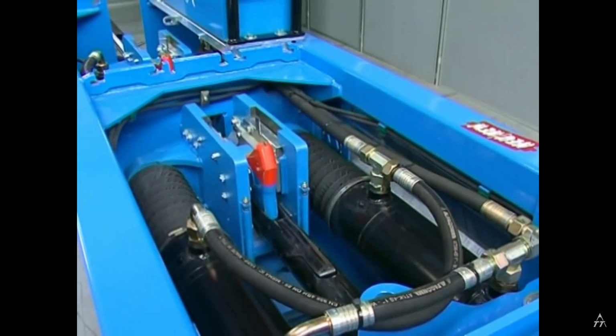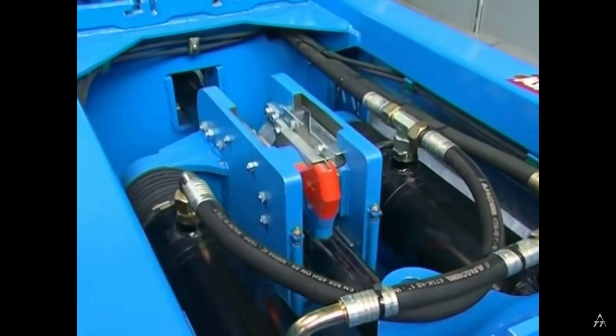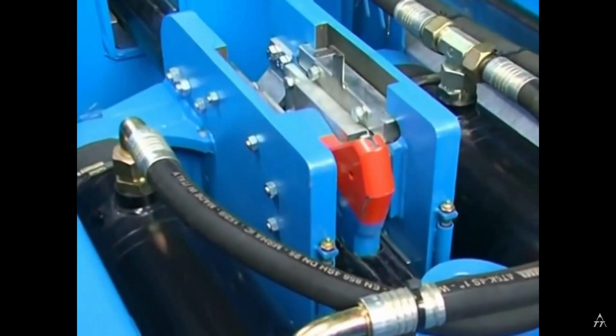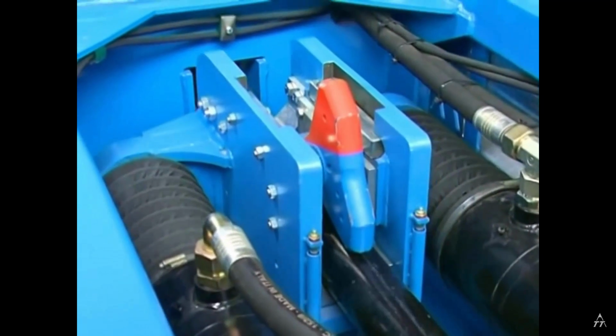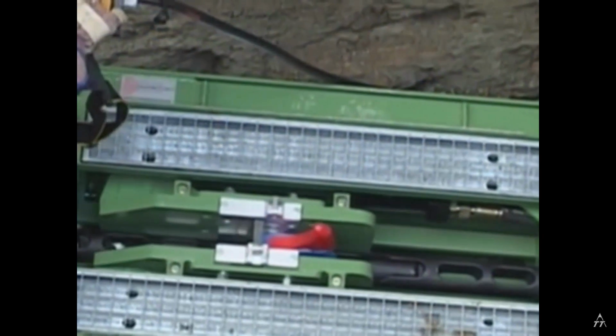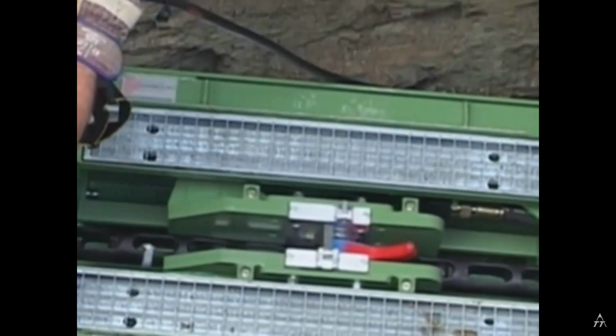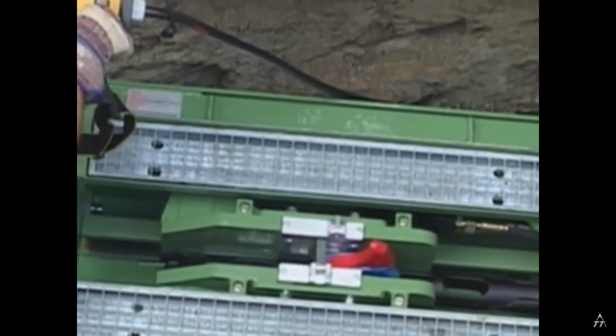Power application is line speed and time controlled. The controlled pulling forces are continuously measured at the new pipe according to technical standards. The bursting rig can be mounted in pits and manholes. Thanks to its universal design, the rig allows the performance of pipe bursting, pipe relining and swage lining jobs with the same basic equipment.